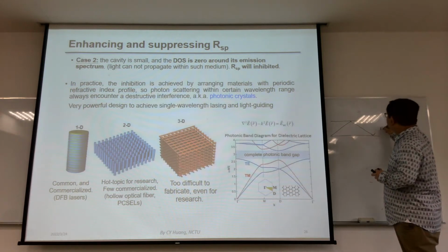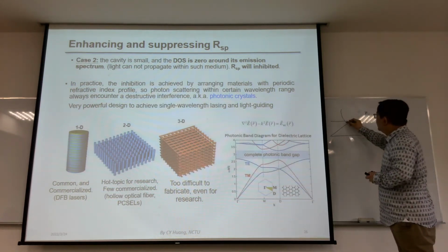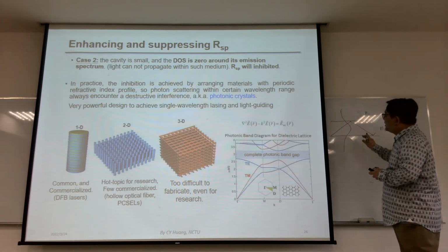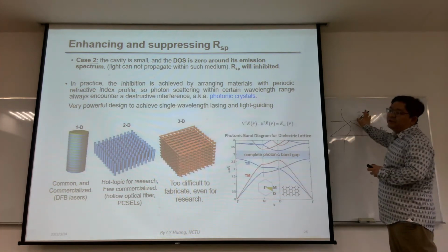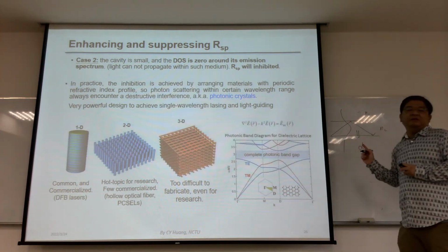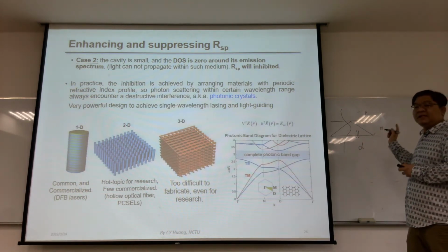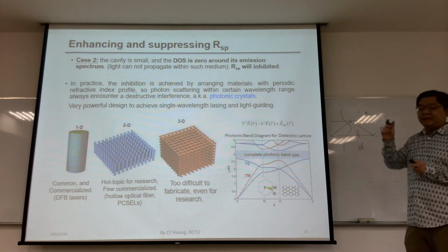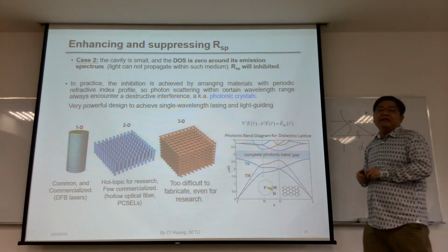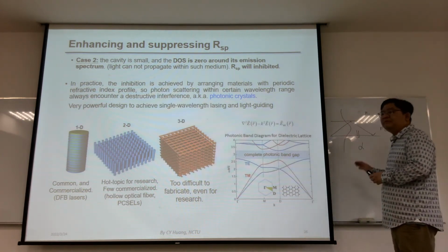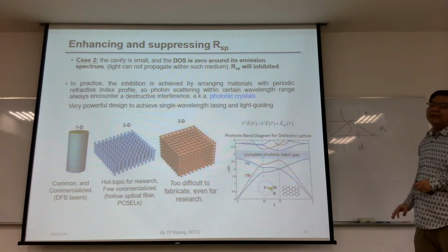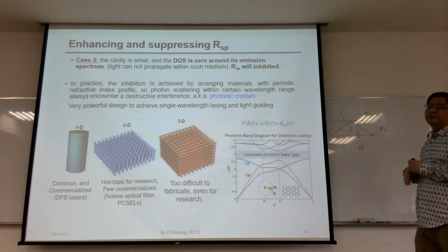And we have n2, n1, and an optical mode. But even when you have total internal reflection, the optical loss alpha is never 0, even below the band gap. There's some additional mechanism, like radiative scattering or free carrier scattering. It could be very, very low, but never really reach zero. We can say almost zero for some applications, but never zero.